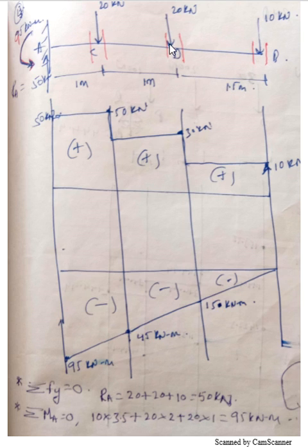And this force, if I consider, is again bending the beam in downward direction, so minus 20 into 1 is minus 20. So minus 20 because of this force and minus 25 because of this moment, so I'll get minus 45. Again I am joining using a straight line because it is a point load.